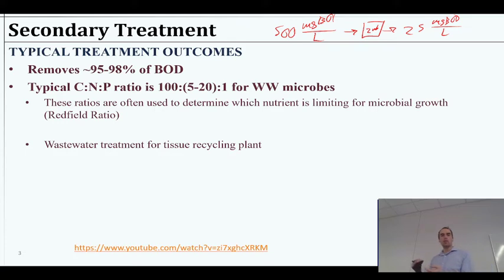So it's a lot of carbon and not a whole lot of nitrogen or phosphorus. Whereas if we're eating food and excreting food and sending that down the toilet and all that, there's a lot more nutrients in addition to the carbon. So at any rate, they had to actually fertilize their bacteria because they had plenty of carbon that they wanted the bacteria to eat, but then they had to add nitrogen and ammonia. So they literally just bought fertilizer from agriculture supply and would just pour it in. They'd just be like, okay, this needs a 5-gallon thing every hour or whatever. It's like they just pour it into their bioreactor because they had enough food.